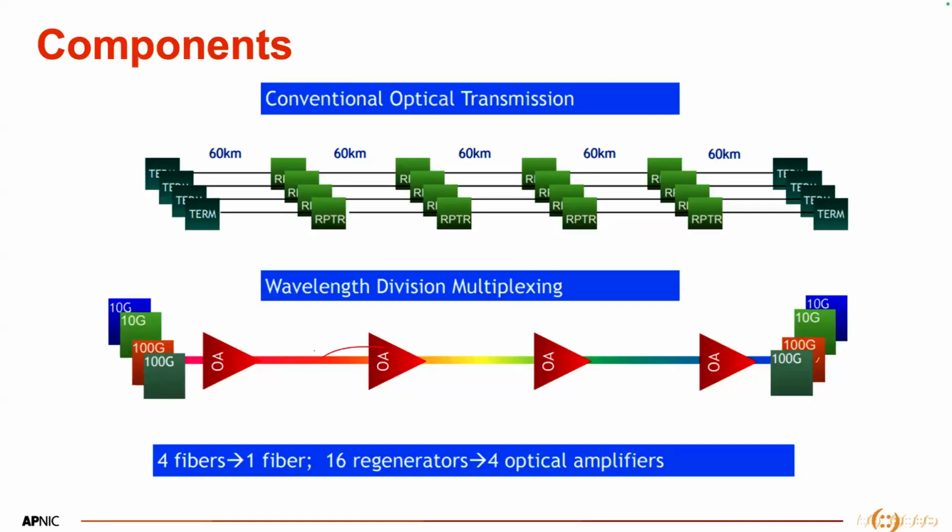And after running the network in a simulator using the loss you have provided them for the fibers, using the loss data, using the number of wavelengths, using the system architecture which they have designed for you, putting all those in the simulator, they will show you what the OSNR is for each and every lambda you will have after you run the network.